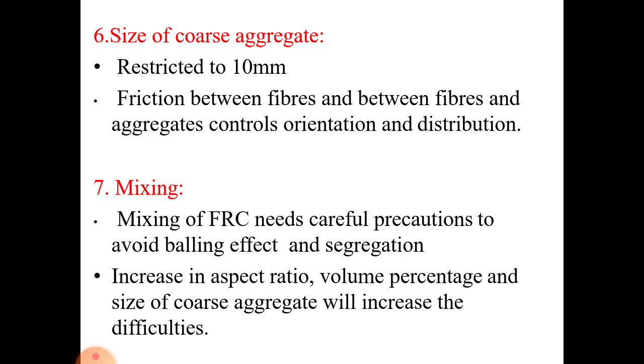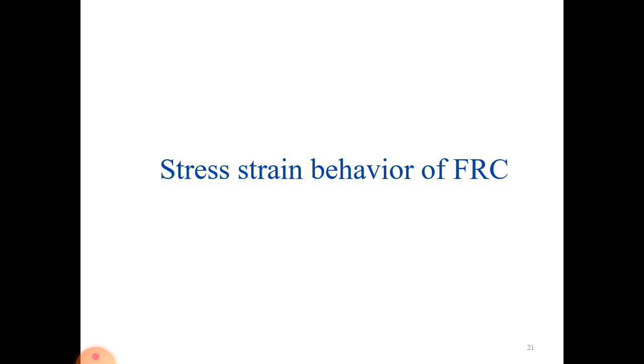Then mixing. Mixing requires careful precautions, in order to avoid balling effect and also segregation. So the chance of occurrence of segregation is high. Therefore mixing needs careful precautions. Then an increase in the aspect ratio, volume percentage and size of coarse aggregate will automatically increase the difficulties.